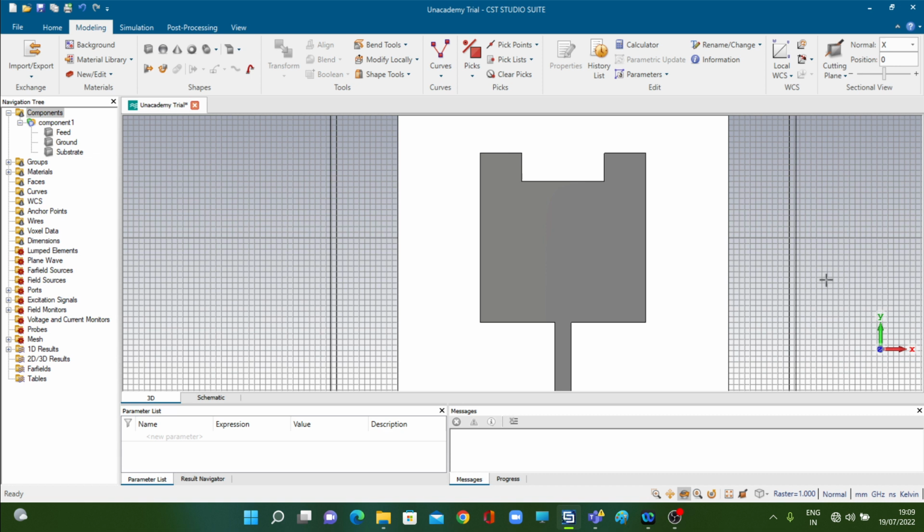The primary contributor in any planar design, which controls the bandwidth of an antenna, is basically the path length of the flow of current. I mean, on this metallic patch that you see in front of you, there will be current flowing on this structure. Only then can there be radiation. So what is the total length of the current that is flowing on this patch? That basically controls the bandwidth.